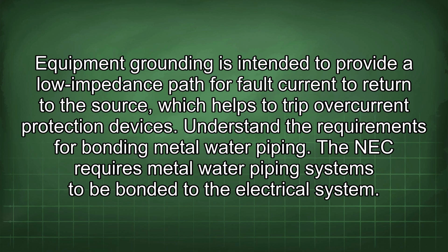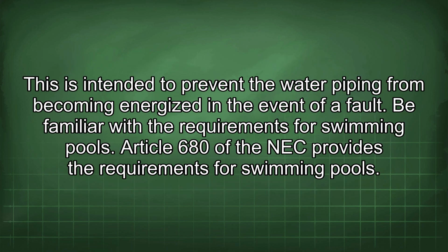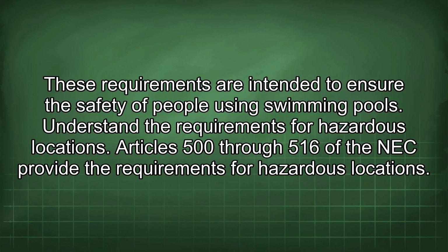Understand the requirements for bonding metal water piping. The NEC requires metal water piping systems to be bonded to the electrical system. This is intended to prevent the water piping from becoming energized in the event of a fault. Be familiar with the requirements for swimming pools. Article 680 of the NEC provides the requirements for swimming pools. These requirements are intended to ensure the safety of people using swimming pools.